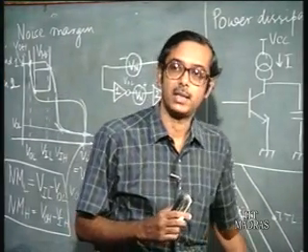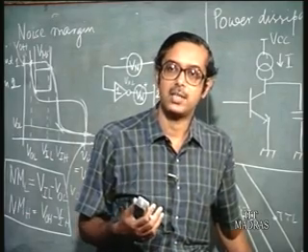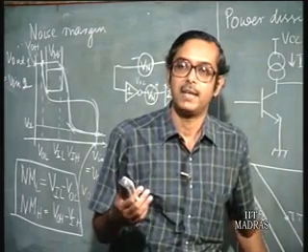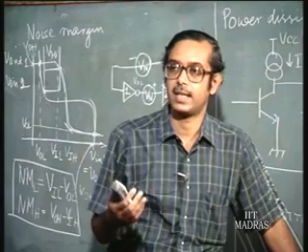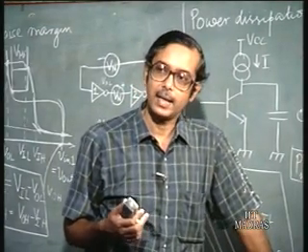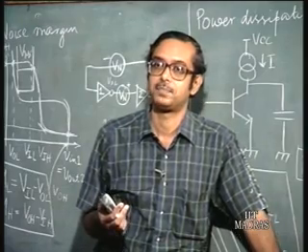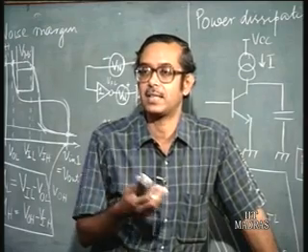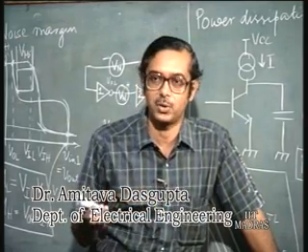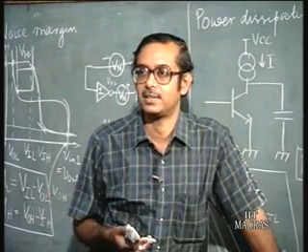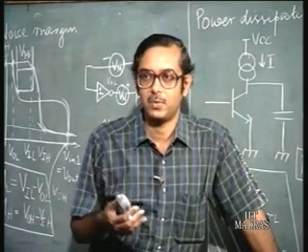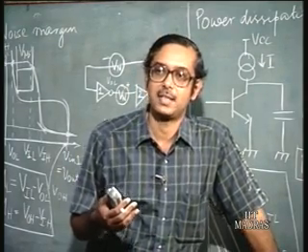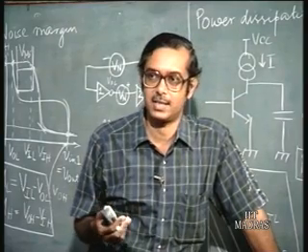So, that is about noise margins, and obviously the larger the noise margin, the better the circuit, because it can operate in a more noisy environment. In fact, the reason why digital circuits have become so important nowadays is that even things which are very much analog, like audio amplifiers, now have digital versions, everything is becoming digital because of the larger noise immunity of digital circuits.